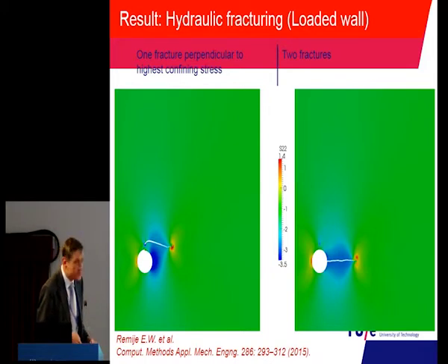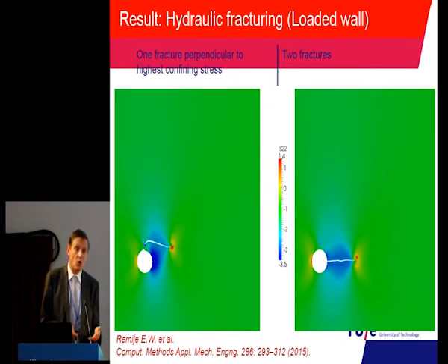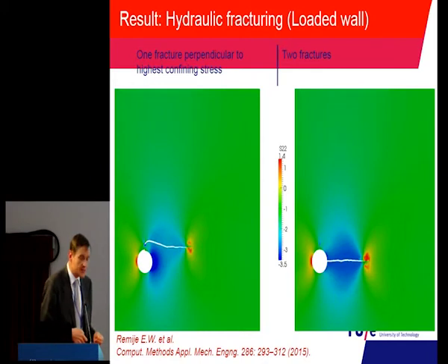And on top of this, we used a separate 1D mesh along the crack, which represents the pressure in the crack. The pressure in the crack, the pressure left of the crack, pressure right of the crack, all three are different. Now, this formulation actually has the major advantage that you can keep your rough mesh and still simulate very steep gradients of pressure.